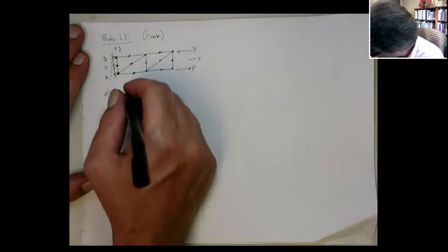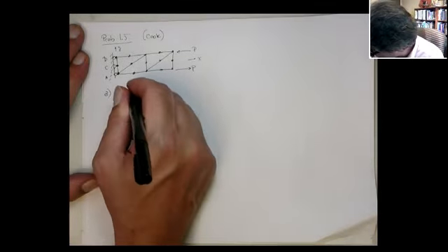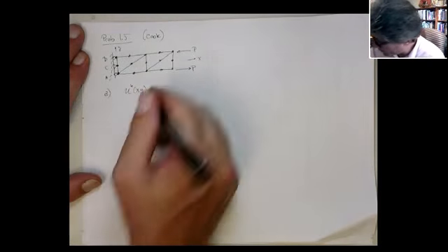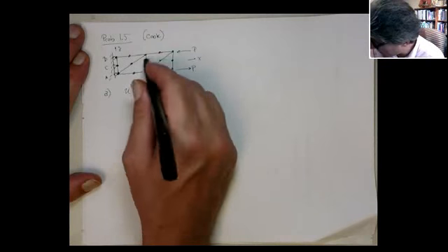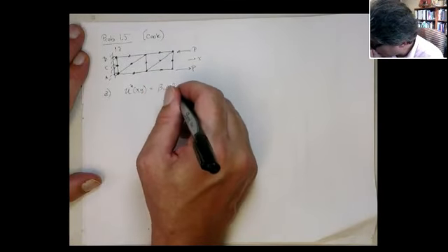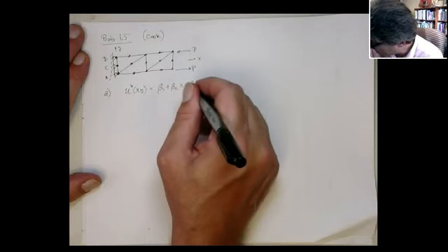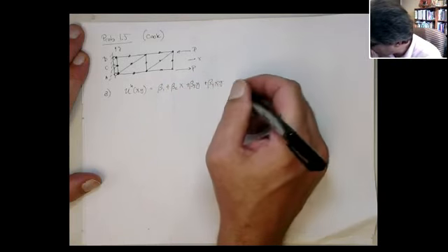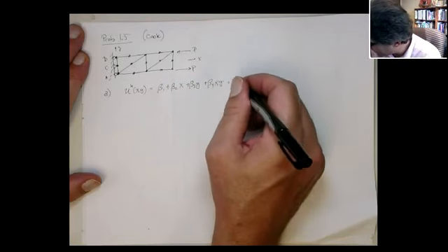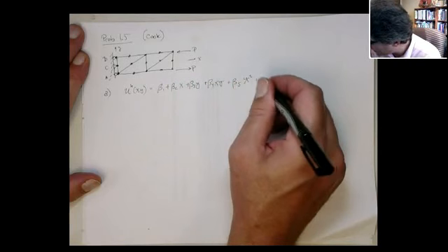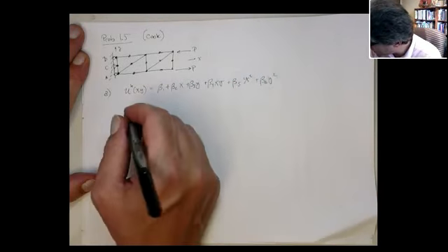Okay, well, the displacement for a 6-node triangle, again, in terms of the betas, we got 6 terms because you have 6 interpolation coefficients, so it's beta 1 plus beta 2 x plus beta 3 y. Beta 4 gives you the byproduct, the bilinear term. Beta 5 is the x squared term, and beta 6 is the y squared term.